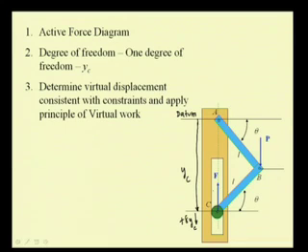And since we have seen that the spring element can absorb energy when the system undergoes virtual displacement, we remove that from the element to idealize the system. So, we represent the spring by its force on this mechanism at this point C. So, this force F is the spring force.